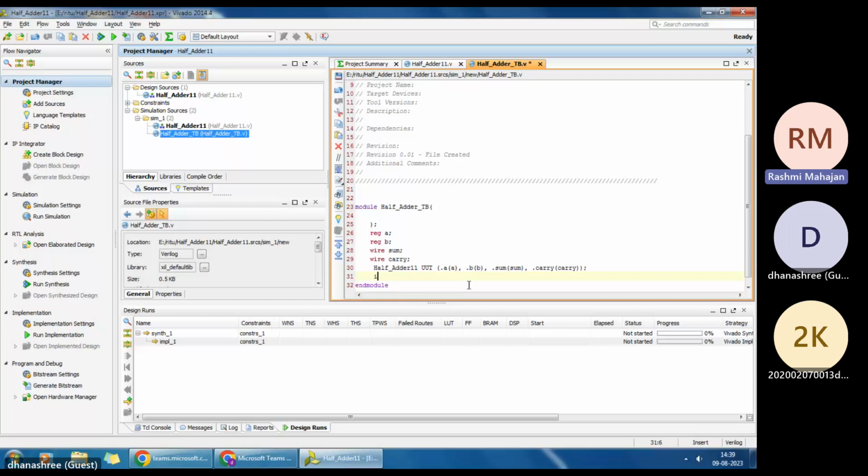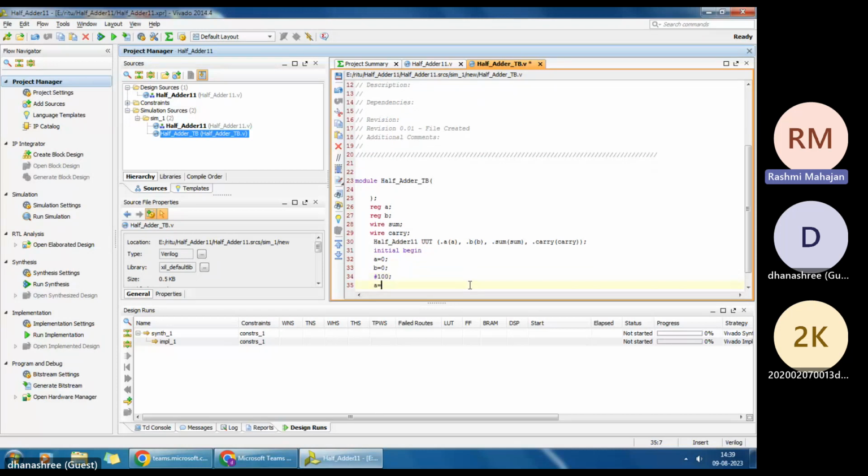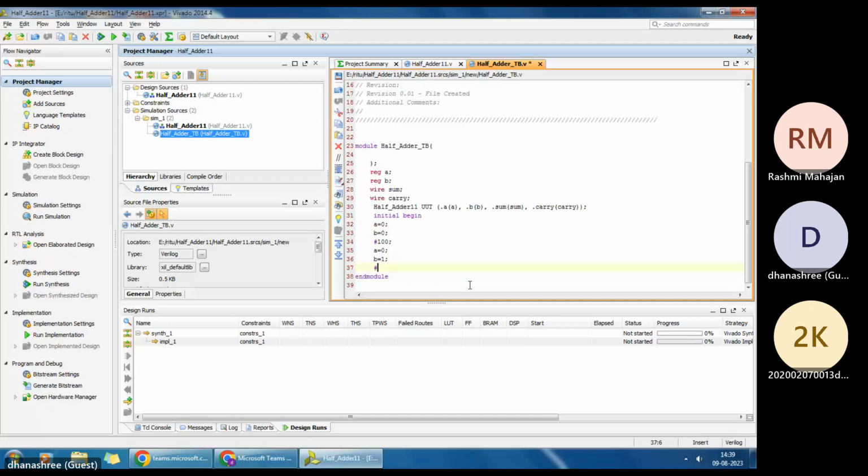The first A represents the register which we have declared in the test bench. The other A is the input which we have selected in our main Verilog code. Very important point: Verilog is case sensitive. So whichever alphabet you use in capital, you will have to use the same in capital throughout the program, throughout the test bench. Otherwise, your port will not get recognized by the program.